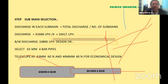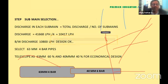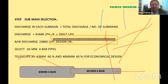Once we have completed the block creation, the design is exactly similar to what we did in online. So what is the total discharge? 41,668, and we have made it into 4 blocks. So 41,668 divided by 4 will give me 10,400 liters. The borewell is discharging 10,800 and my requirement is 10,416, so my design is correct. Therefore, from the selection of the pipeline, I can start with 63 millimeter, which can carry up to 14,000 liters. So we can go for a 63 mm at 60% telescope and a 40 mm telescope for an economical design. This is how the design for the submain has been done.